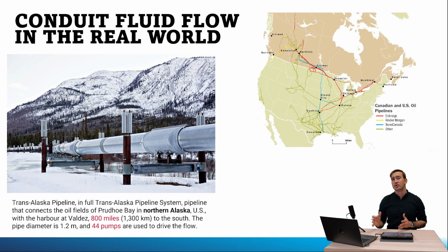Now, if you were an engineer and you were designing an advanced pipe system like this that spans countless miles, you're going to have to take into account friction. The things that are going to be most important to you are to, number one, determine if the flow in the pipe is laminar or turbulent, and to, number two, determine the pipe size and the roughness, which essentially translates to the internal friction related to the material that you're choosing.